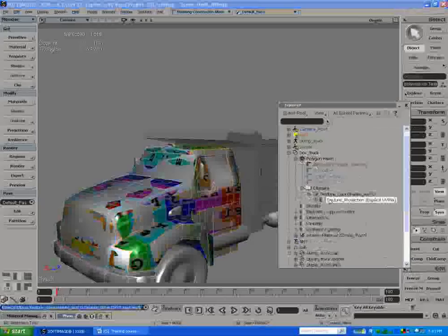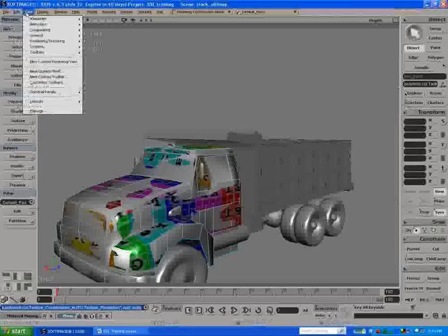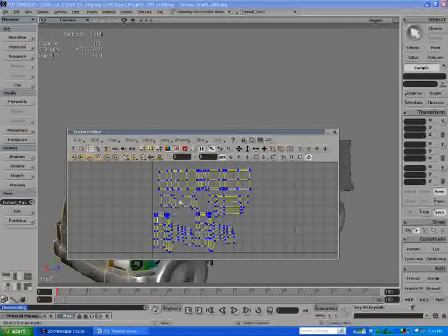tangents. Okay, so what this has right now, it has some UVs on it, and that's important. And the UVs are non-overlapping. That's also very important. So I've got my UV set up this way. You can see they're nice, laid out pretty well, and there's no overlapping UVs here. I could have rearranged them a little better than this, but this is good enough for the moment. Ideally you want to not have some seams in certain areas, but again here would be fine.